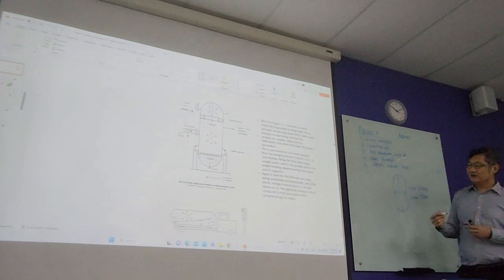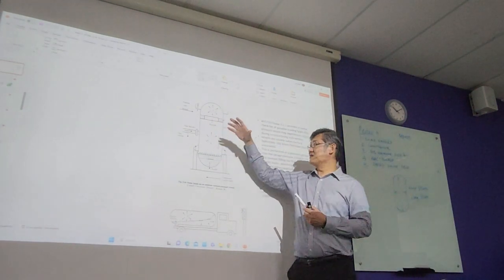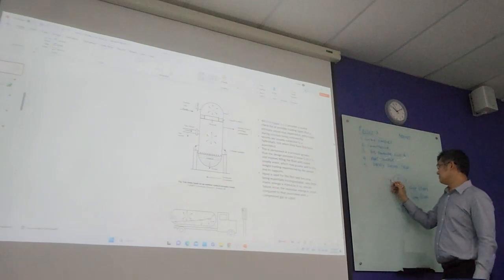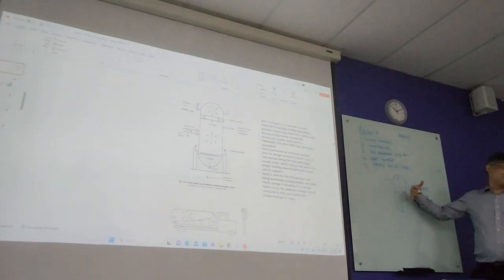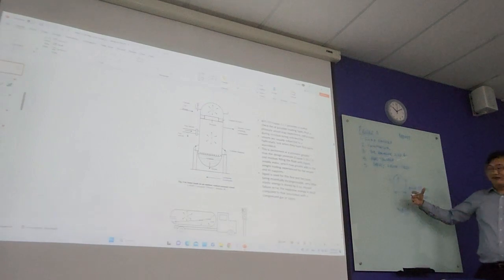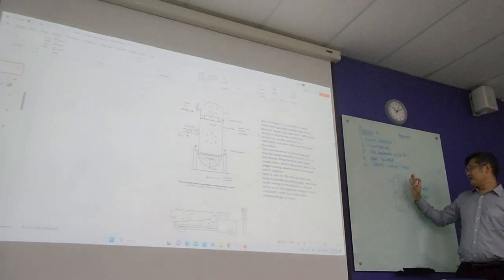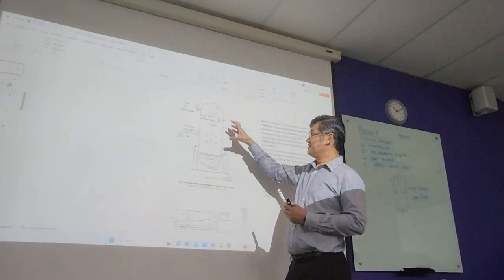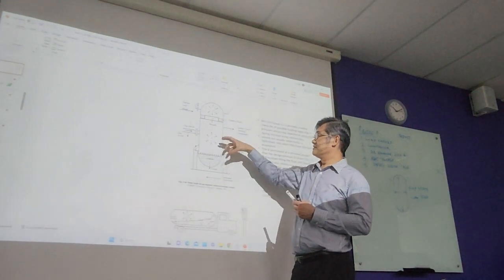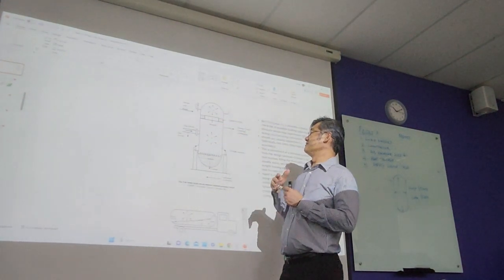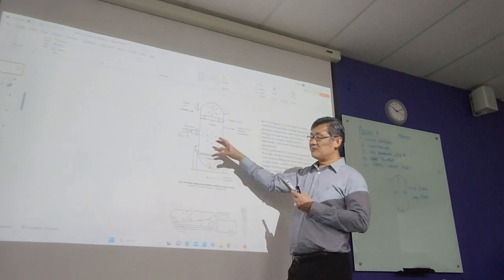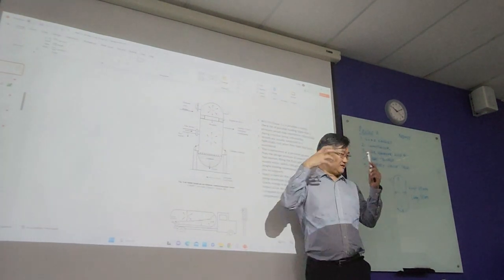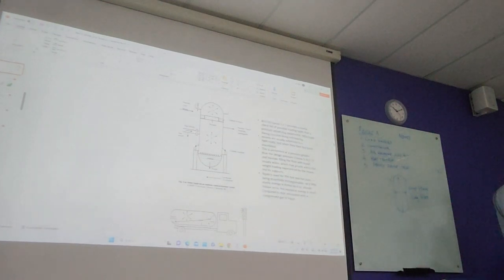We also have what we call exterior loads, let's say subject to the wind, earthquake. The weight of the cylinder itself is exterior. You have internal pressure, you also have exterior pressure. So over here they show you, beside internal pressure, we have all these factors: weight, wind blow, vibration. If, let's say, this one is portable, it is subject to transportation, those vibrations during the journey. So you need to know. Over here they show us.